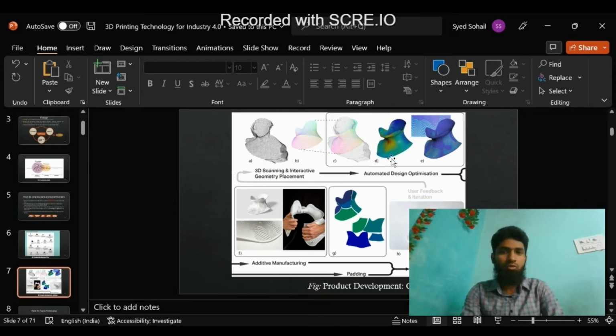So to be able to do that, you have to see the different stresses generated at different positions, and how can we better accommodate those movements in terms of the geometry that we are keeping, and the material as well. So now they have gone for, instead of making one full piece, four different pieces, or more, four I think here. So that is how they were able to produce that. Simulation as well was carried out, as you can see, to predict the stresses, and then they went for a final 3D printed part so that we can have that final product.